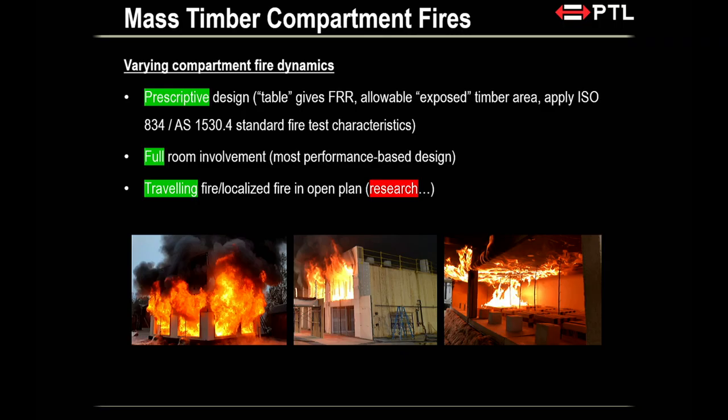Why? Because it's a completely different pathway for us. In prescriptive design, we read the table and that's it. But in performance-based design, we get questions about fire dynamics. Have you considered the contribution of timber? Have you considered how much window is breaking? So it's a completely different ball game. Some of the slides that I'll go through will explain this a little bit further.